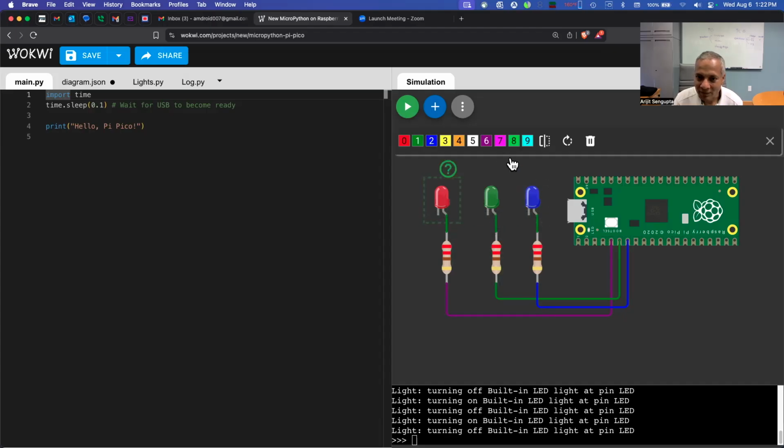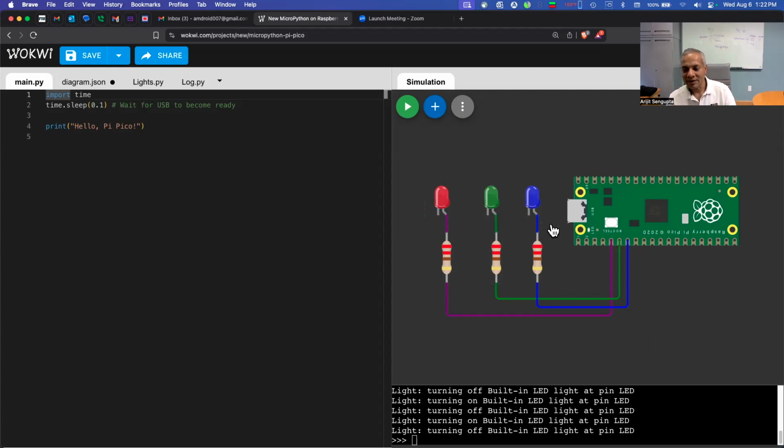And once again, if you want to change the color, I changed this guy too, and this one to blue. All right, so one side of our LED is connected. Again, what we did, we took a wire, went from pin 3 to one end of the resistor. The other end of the resistor we connected to the anode, which looks like the longer pin of the LED. Same thing we did pin 4 to the resistor to the anode, and then pin 5 to the resistor to the anode. Now the other side is pretty easy.